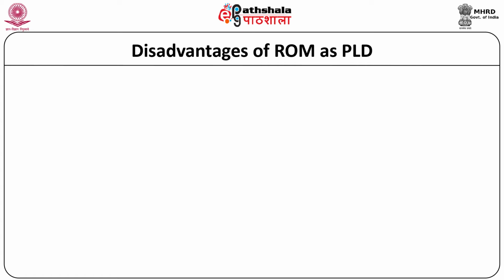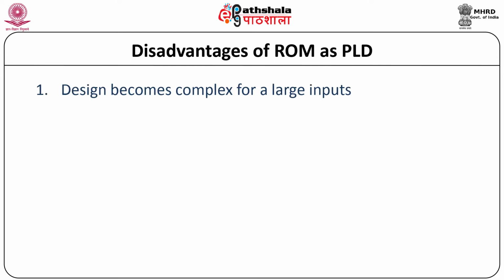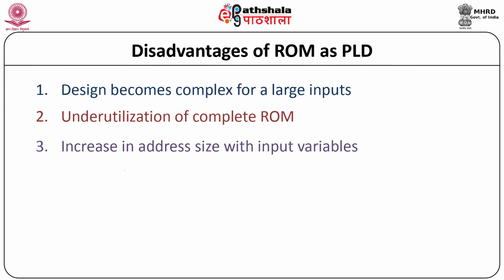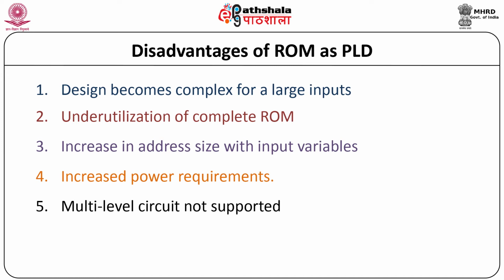There are a few disadvantages of ROM as PLD. First, design becomes complex for a large number of inputs n. Second, it is possible that there is an underutilization of the complete ROM circuit for simple applications. Third, increase in address size with increase in number of input variables. Fourth, increased power requirement. And last, it does not support multi-level circuits as no outputs are brought back as inputs.